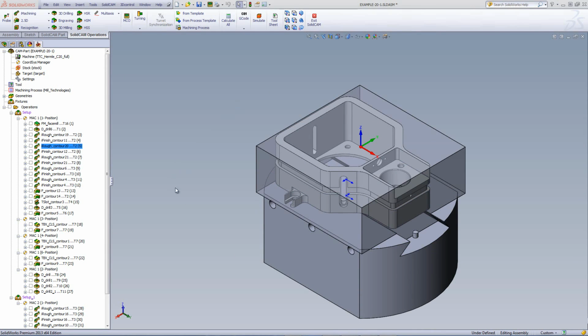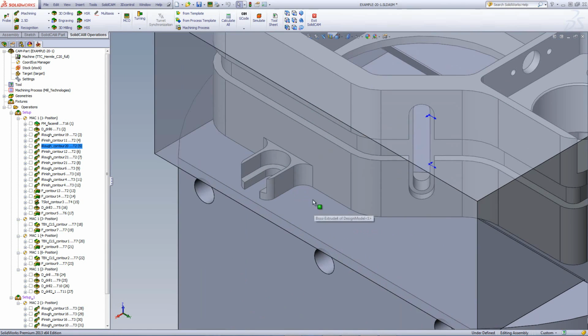Now I needed to complete the outside by milling down from this edge over here down to the very bottom over here. So for that, I've done another iMachining operation based on the first one, just with different geometries and different levels.